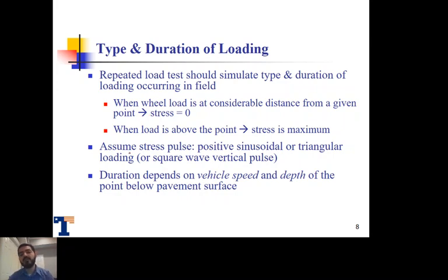Therefore, we try to assume that there is a stress pulse. Typically, it's positive sinusoidal or triangular loading. What does that mean, sinusoidal loading? Let me try to draw it here, something like this. So we apply the load, we have a rest time, we apply the load, and we have a rest time, and so on and so forth. This is sinusoidal. It's not really a pointy loading. It's gradual. So from zero right here it goes all the way up to the maximum and gradually goes back to zero. And then here we have a rest time, and then another loading will start.